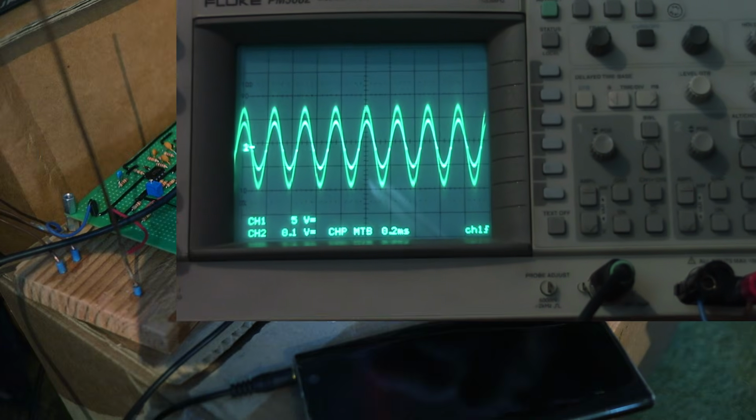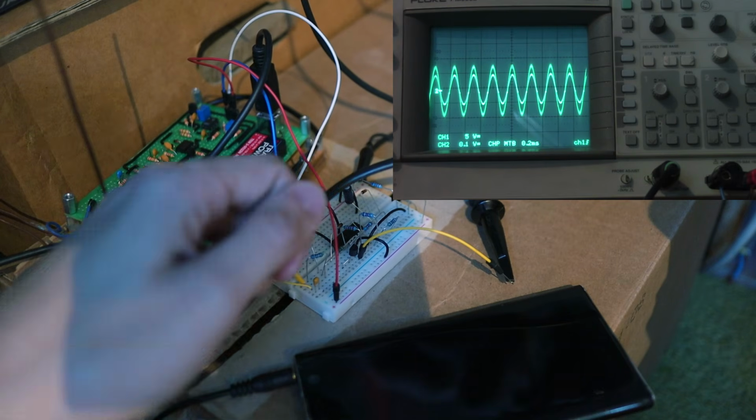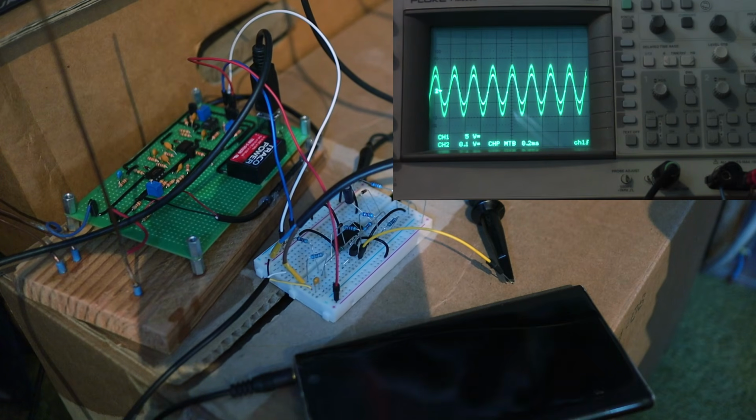But as we've just seen, it is also possible to make a more mild compressor that allows the amplitude to rise a little bit. And we can do this by switching out components in this case. If we had used potentiometers instead of resistors, we could do it by turning a few knobs, but I didn't have potentiometers laying around, so I just used fixed components.